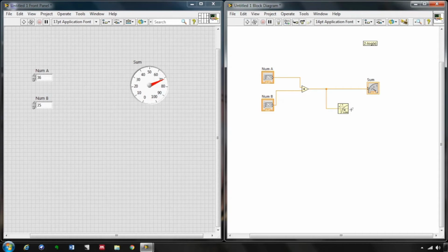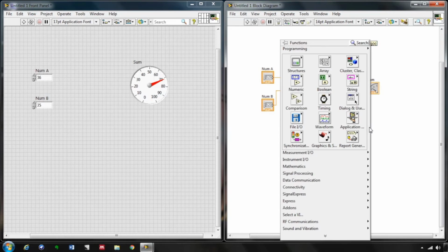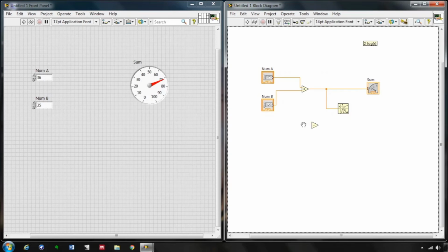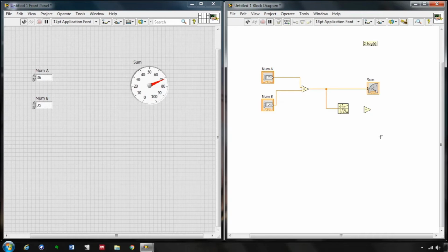What lies at the other end of the logarithm is the log of the sum, which is log x. Now the other thing I wanted in my expression is the subtraction. So I will go to the functions palette again, go to the numeric, choose subtract, place it near the logarithm part, and I want this logarithmic part to get subtracted from 2.